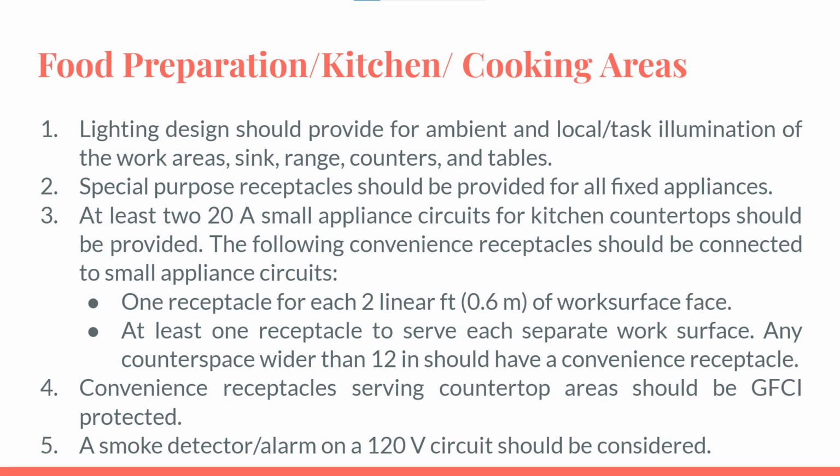The following convenience receptacles should be connected to small appliance circuits. One receptacle for each 2 linear feet or 0.6 meter of work surface space. At least one receptacle to serve each separate work surface. Any counter space wider than 12 inches should have a convenience receptacle.